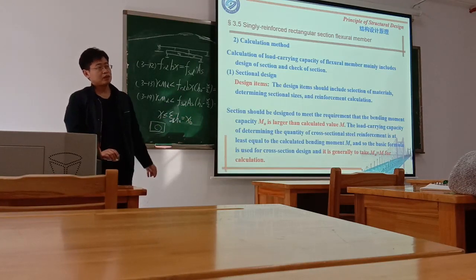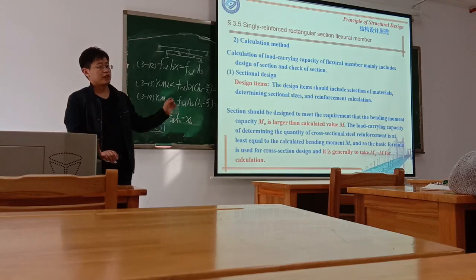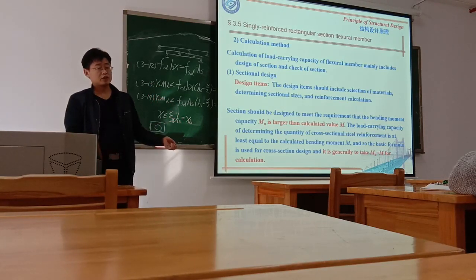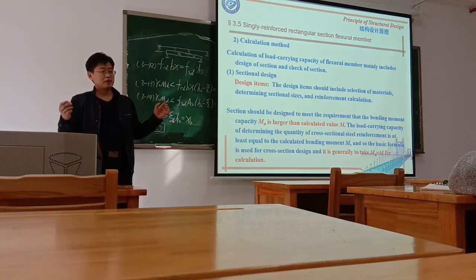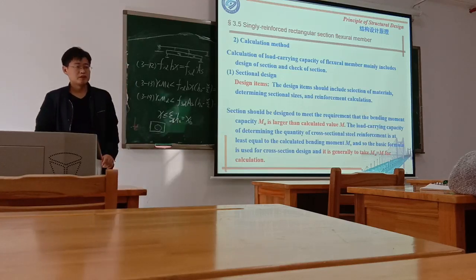Even 50 meters sometimes they use it, but of course they use a pre-stressed T-shape. Normally 20 meters, even 30 meters, can just use reinforced concrete. It's not necessary to use pre-stress, but using pre-stress is good. But the construction is relatively more complicated compared to reinforced concrete.